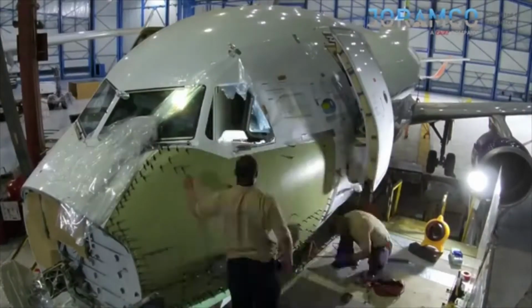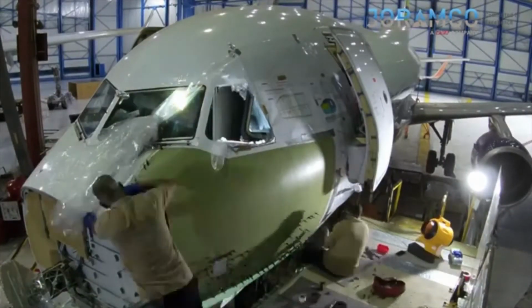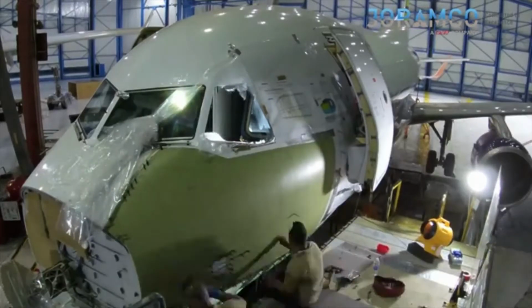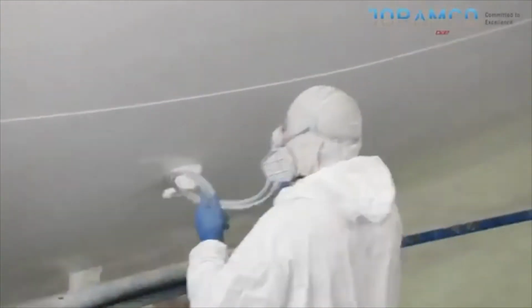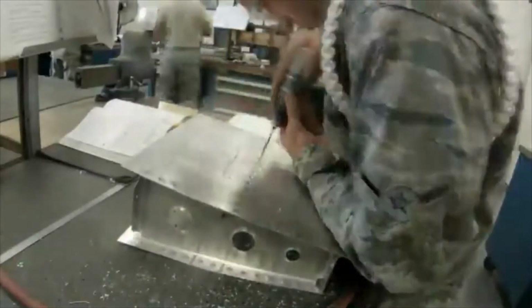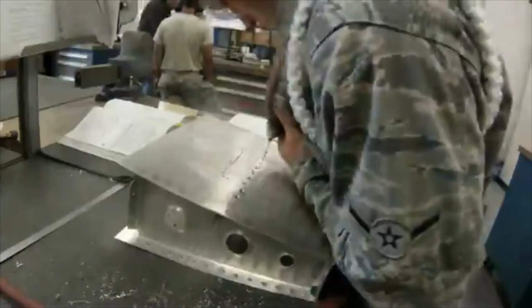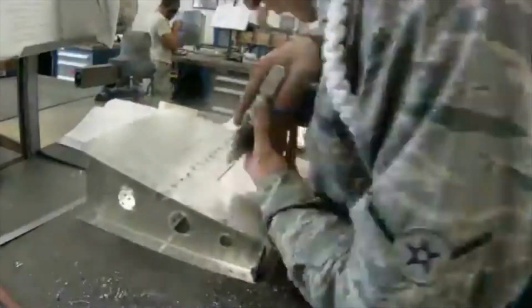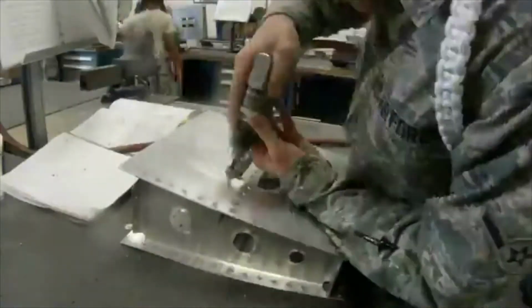In actual practice, repairs must be strong enough to carry all of the loads with the required factor of safety, but they must not have too much extra strength. For example, a joint that is too weak cannot be tolerated, but a joint that is too strong can create stress risers that may cause cracks in other locations.